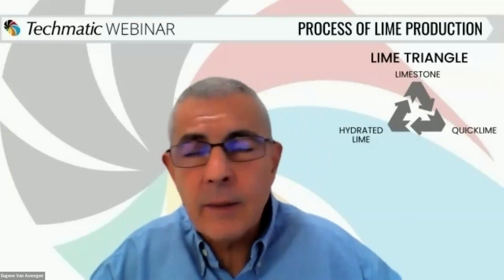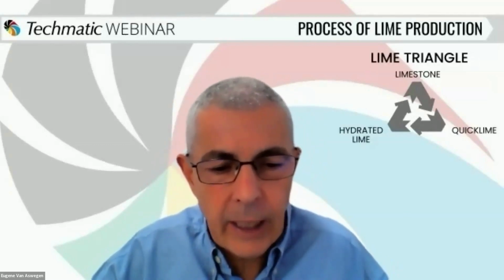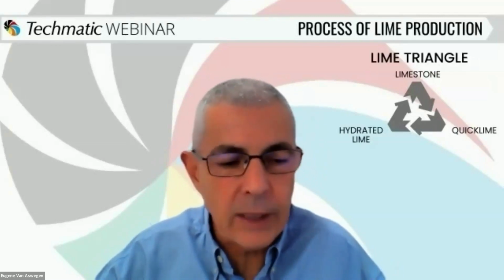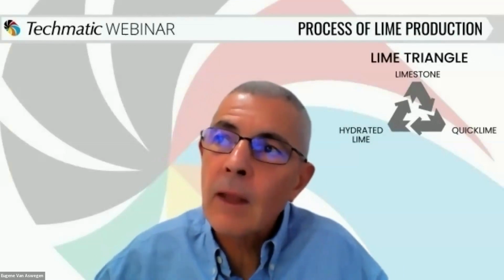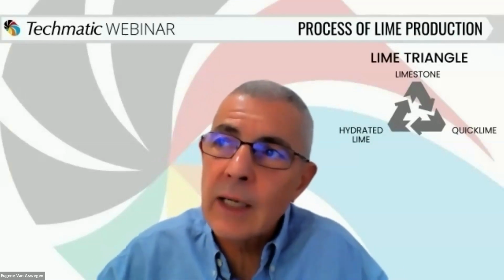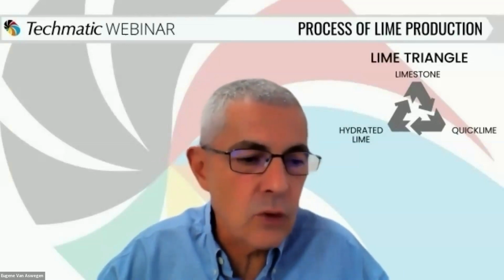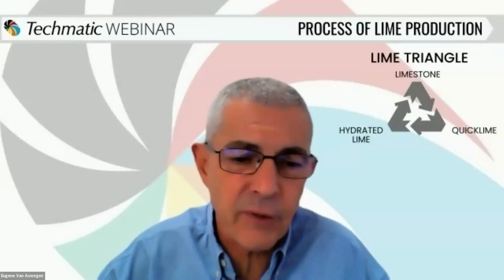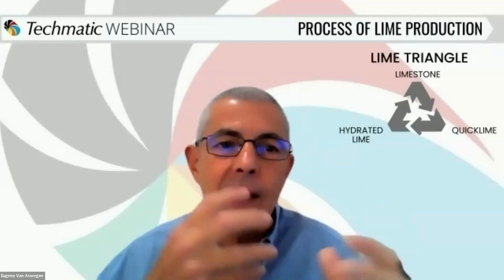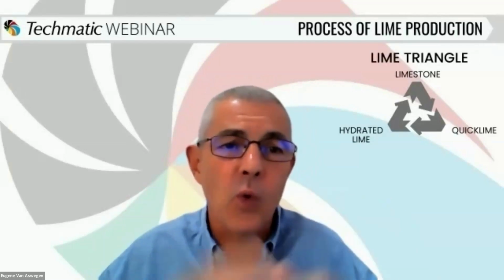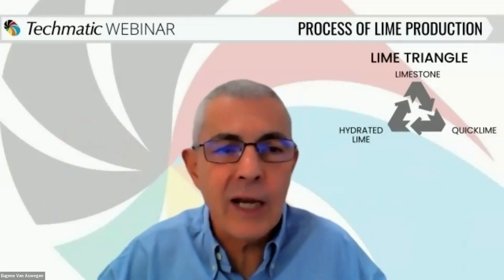Now, you may ask why I am giving you a range. That is because Mother Nature and burnt lime have a love-hate relationship. As you produce burnt lime and it comes out of the kilns, if it's raining in the Northern Cape on that specific day, you will battle to continue having an 86% available lime, because, as Karsten alluded to earlier, the unslaked lime particle starts reacting with the water or the moisture in the air, which reduces your available calcium.